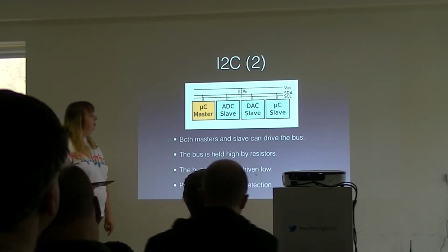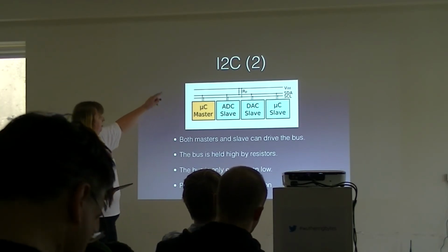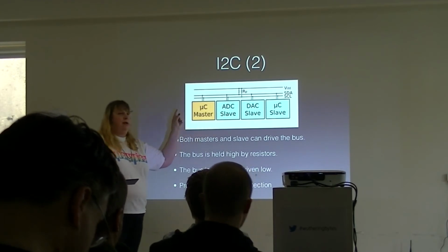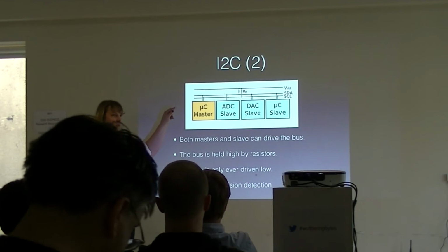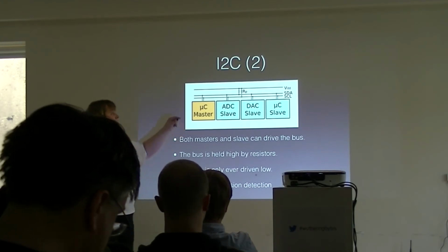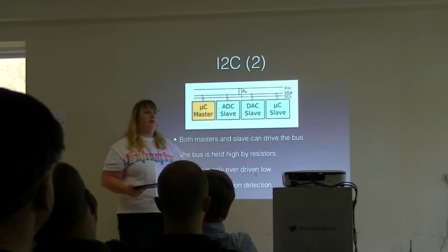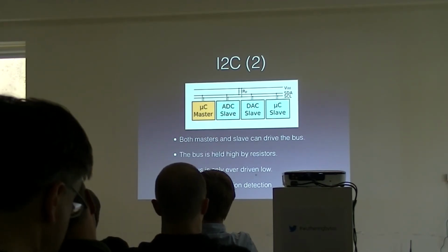Slightly interesting thing is, you don't really need to worry about it, but none of these ever actually set the output high. They're either high impedance or they set it low. And these go high because there are typically 2 resistors connected to the supply line.